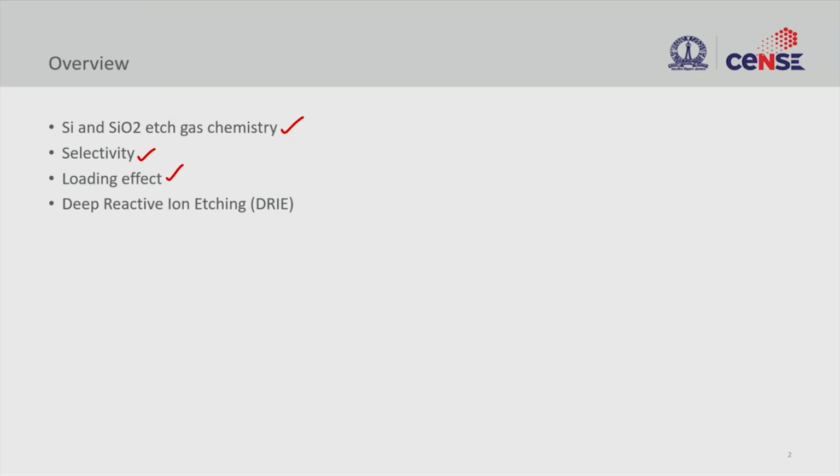The loading effect is caused by various factors in the design and also the process. So let us understand what the loading effect is, and then finally we'll also look at a special type of etch called deep reactive ion etching, which is used in modern day integration.